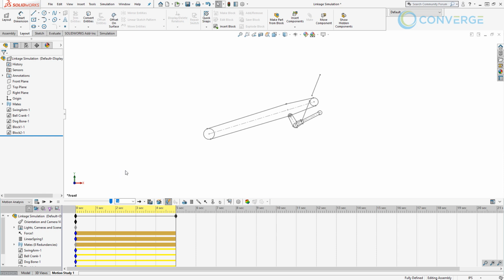And again, you might be wondering, why are we bothering doing all this? Well, the first thing is this helps us address not only the size of the damper and spring and the forces associated with that, but also the geometry of our linkage. We might decide to make the swing arm longer or shorter. We might decide to move the location of this linkage mount in this case, or where the suspension actually mounts if we're talking about a fixed shock situation. We might also decide to move the upper mount for the suspension. We might need to move things around, say we're planning out the frame and all the attachment points.